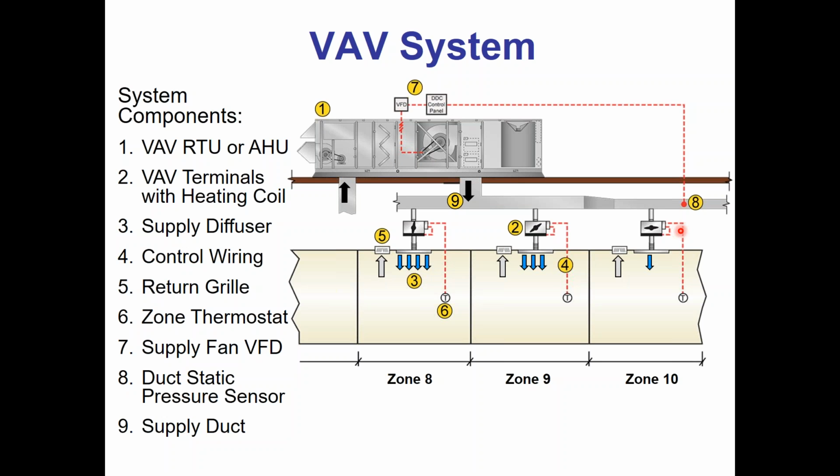You could have a VFD on a rooftop or air handler that is set up for what we call staged air volume, and that would be a 2-speed fan. So it might have a VFD on it, and a lot of rooftops have a VFD now. In fact, all the rooftops we do above like 6 tons for code compliance, we put a VFD on them in Illinois. So you're going to see a lot of VFDs on rooftops, but that does not mean it's a VAV unit. Those are 2-speed VFDs. The VFD only runs at 2 different airflows, 67% and 100%. That will not work on a VAV system. I have to have full modulating control and a static pressure sensor down in the duct system.